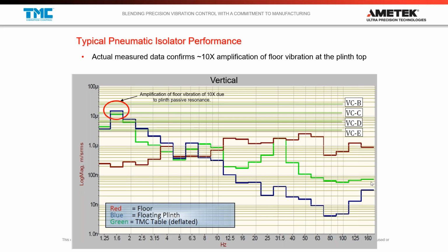This could be from noise generated on the table, or acoustic noise in the facility. It's probably not transfer; it's more likely due to resonances above the table and resonances of the rigid legs themselves. If it was coming up from the floor, we'd see it in the floor data, which is actually the blue data, not the red data.